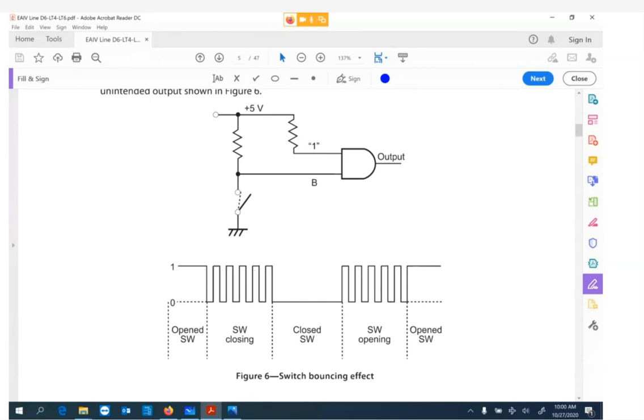We had a mag starter at the mill that was kind of experiencing this in regards to a photo eye. We didn't have a debounce timer in there, and the mag was banging itself to pieces. Basically, it was quite a big mag. I think it was a size 3 mag. So it's just something in the logic that we forgot to do. Once you put a debounce in there, we're good to go. But something called an RS latch could help eliminate this.